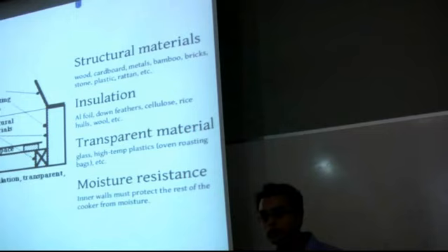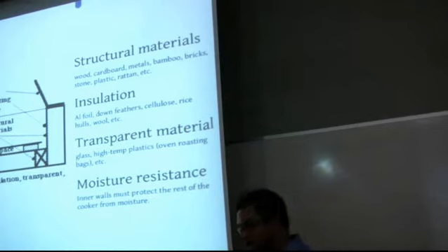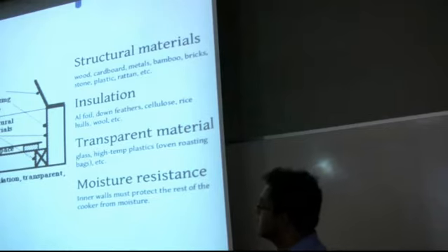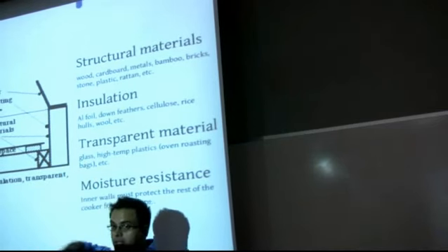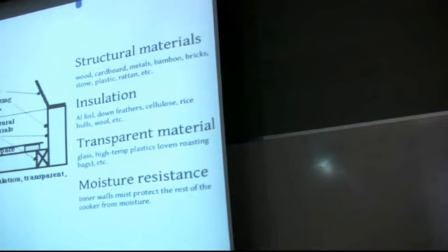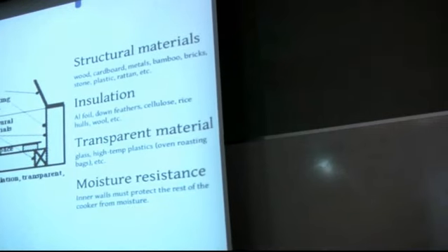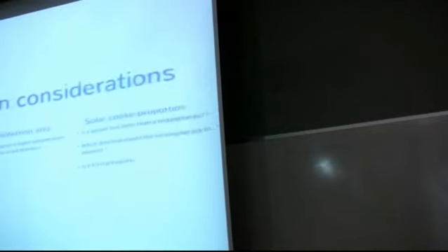One is you're going to lose energy, because it's just like the air is taking use. It's water, it's the same principle. Secondly, if water vapor escapes, it can attack whatever material you have outside, especially if you're using cardboard or something. So that affects the durability. So you want to have some sort of vapor barrier if possible. So some interesting things to consider.